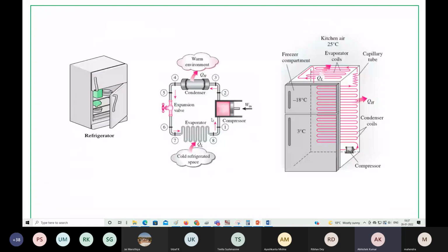See here, in case of your refrigeration system, let us come from this point. Here, this is vapor actually. Why is it vapor over here? Here, your refrigerant has absorbed the heat from the foodstuff in the refrigerator or otherwise in the room where we are staying. That heat is also absorbed by your refrigerant, and this refrigerant got evaporated in this evaporator.